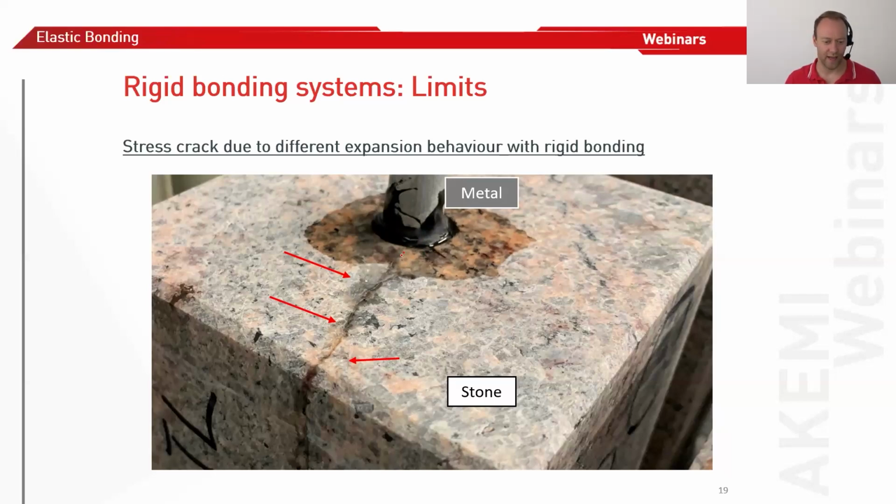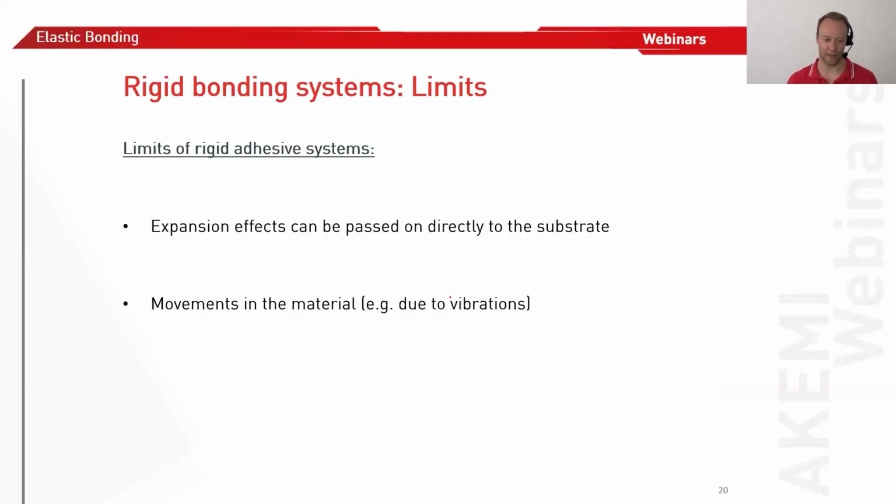In this case, you get a lot of force on the stone, and then it could get some cracks. This always depends on the application and on the stone material, and this usually will not happen in an interior application. You don't have much temperature change there, but when it comes to outdoor applications, it's a thing, and you have to have it in mind. So, stress cracks due to different expansion behavior with a rigid bonding system.